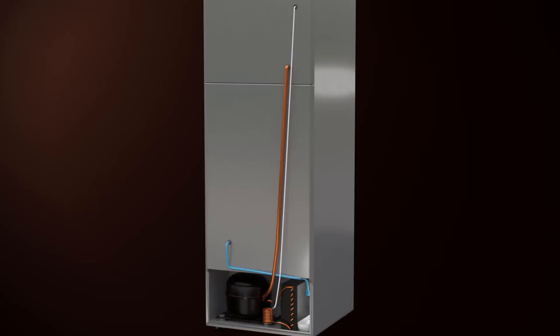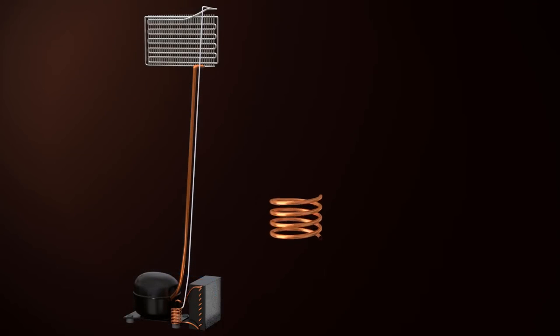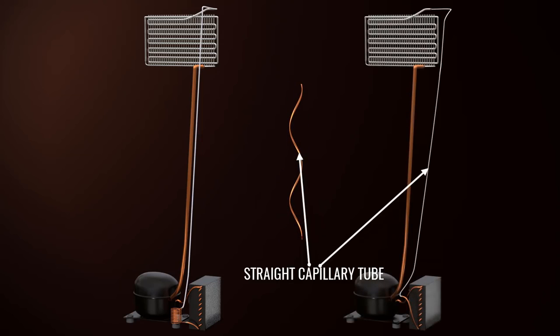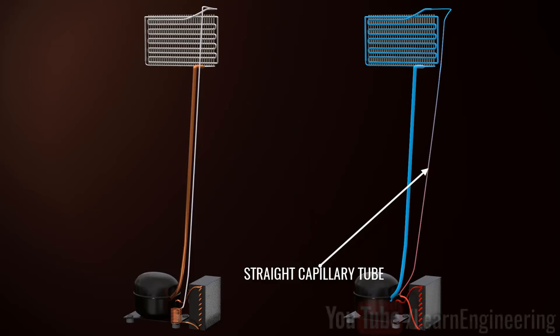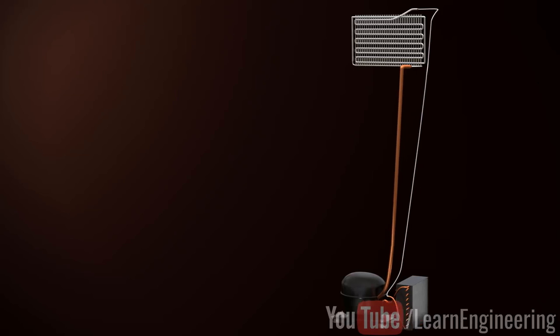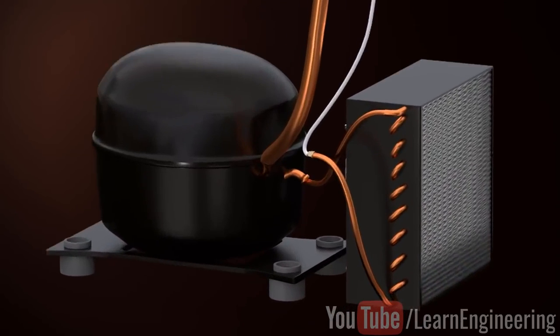However, if you check your home refrigerator, you can see only one line on the outside. Why is this the case? The most crucial part of the refrigerator is the capillary tube, which need not be a spring-like device. It can be a long, straight tube, as shown. Temperature variation in the new, straight capillary tube is depicted here. You see only one line on your home refrigerator because this straight capillary tube runs inside the evaporator exit coil.